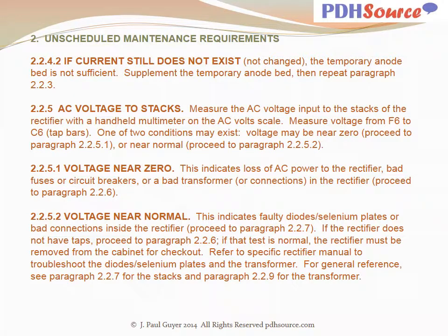If current still does not exist, not changed, the temporary anode bed is not sufficient. Supplement the temporary anode bed, then repeat paragraph 223.